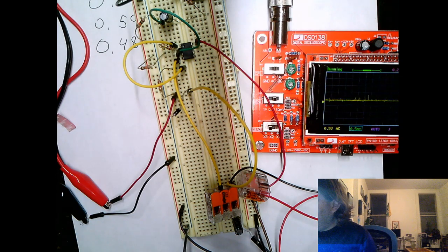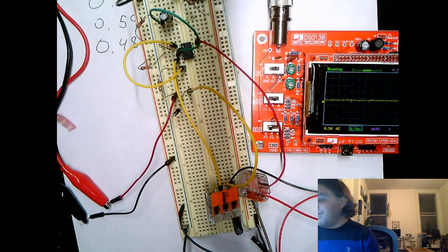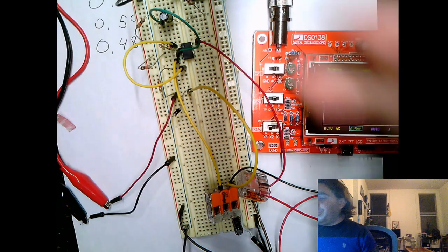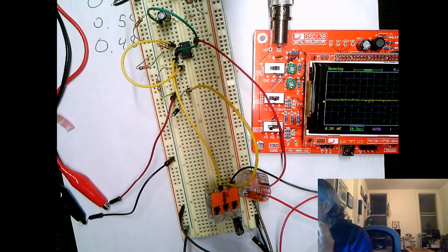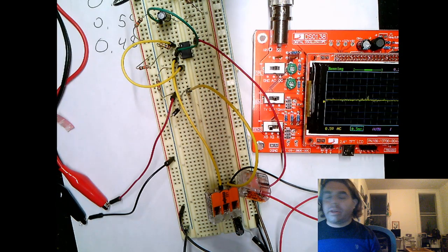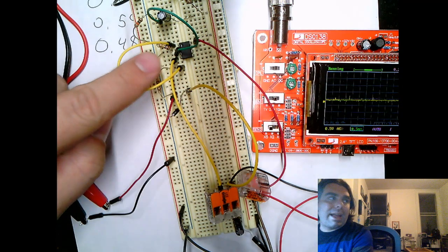So this is all distortion is, right? We're simply sending this amplified signal through this diode, right? And I just built a quick non-inverting amp right here with a gain of 10 just so I could hear it more clearly. Now, if you're doing this for your final project, you might find that a gain of 10 isn't quite enough. If you want this to sound more distorted, you can increase this gain.